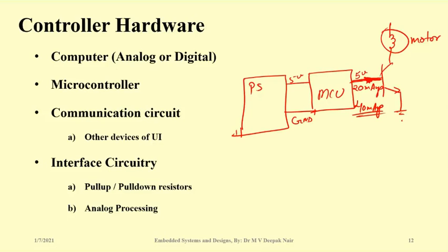You can use LEDs, but it cannot drive a motor, because the motor needs, assume, 5 volt and 500 milliampere. Now the game has changed. The microcontroller can provide only 20 milliampere, but the motor needs 500 milliampere, though the voltage is the same. So assume your power supply can provide 5 volt and 2 ampere.